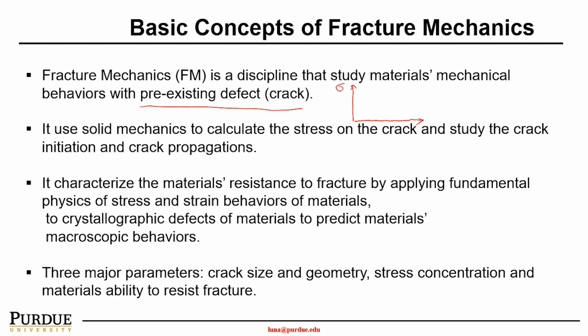Let's use steel as an example. It develops a linear behavior at the beginning, and then the material reaches the yield stress, goes into a plateau, reaches the ultimate stress, and then breaks. So here it's sigma yield, sigma U, sigma fracture. In this case, we consider this material perfect.